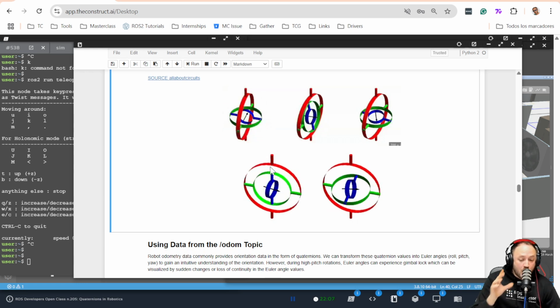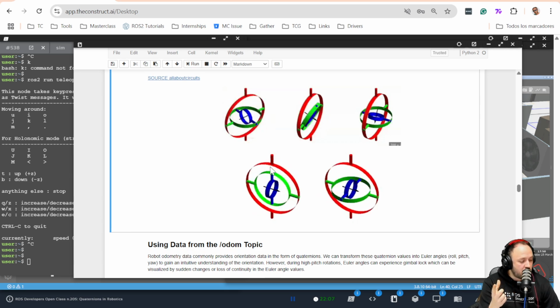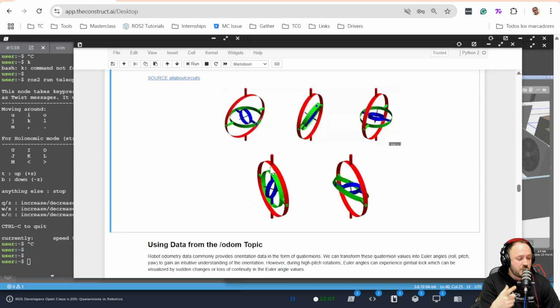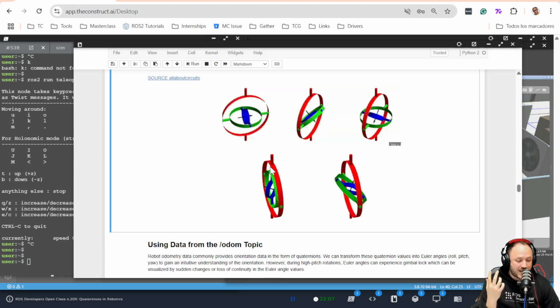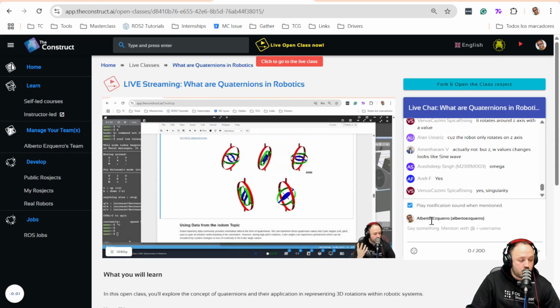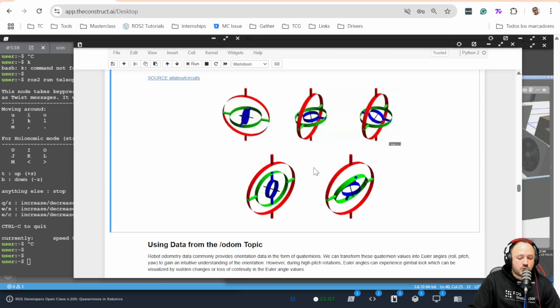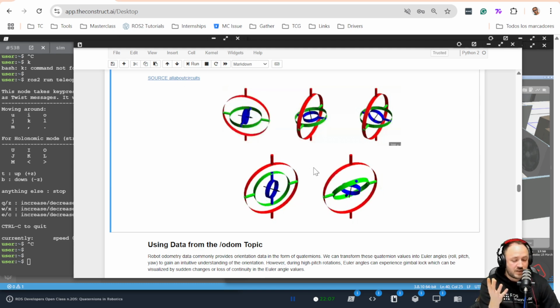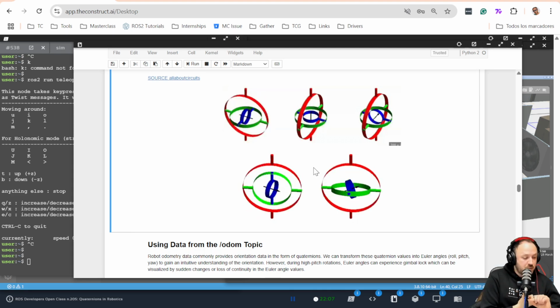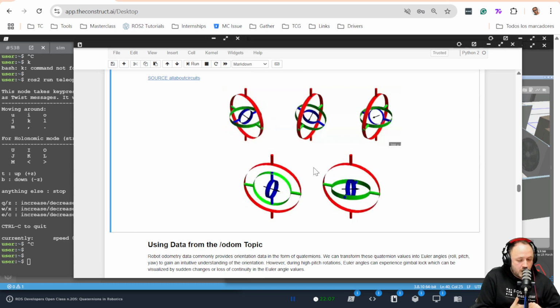Then when this happens, their rotations are essentially the same, which means that the system loses a degree of freedom. Okay? This is known as a singularity, as Venus was saying, and this can cause problems in this kind of robotic systems if we work with Euler systems, meaning roll, pitch, yaw, okay?